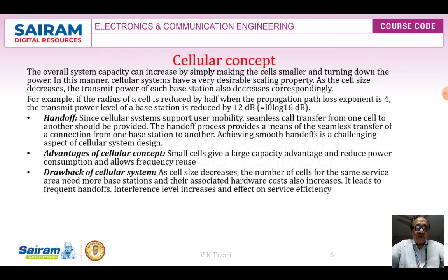The base station provides the allocation of the channel in terms of frequency in FDMA. In terms of TDMA, it will be logical channels, whereas analog channels are FDMA, FDD, frequency division duplex.